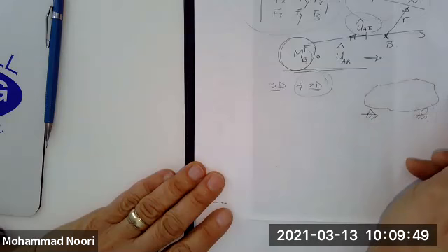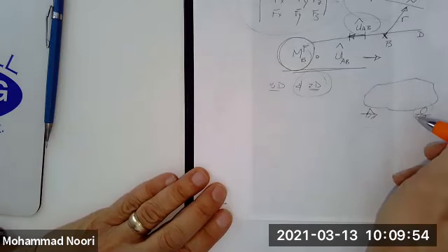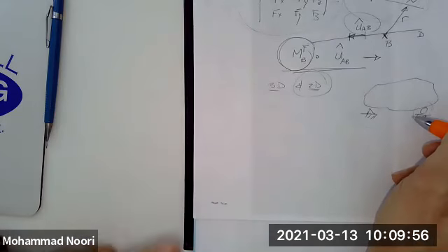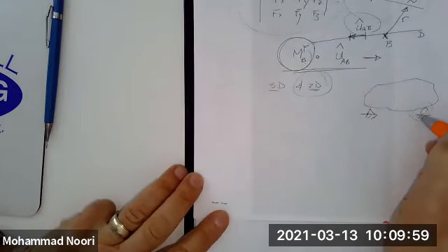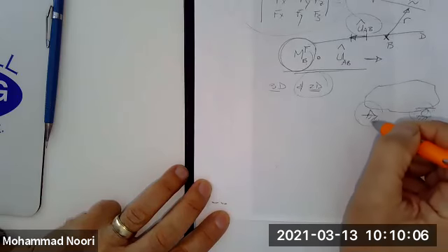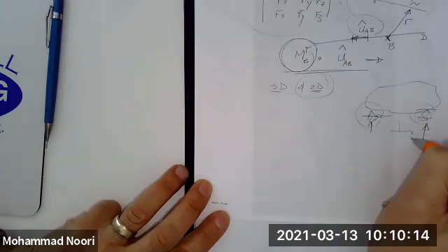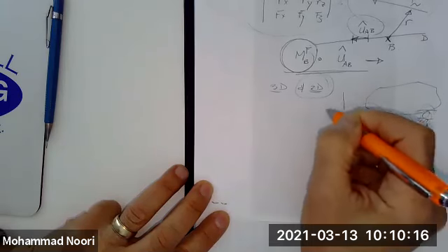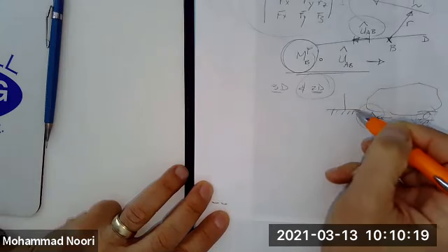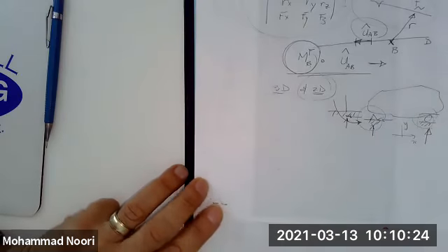In 2D it was easy. These external supports represent no more than 3 types of forces. A roller represents a single force that is perpendicular to the potential direction of motion. A pin represents 2 unknowns that are basically along the X and Y directions that you set up. And if you have a fixed support, that represents 2 unknown forces and an unknown moment.